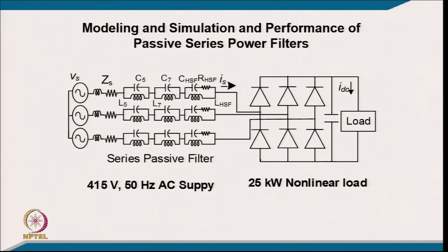Earlier only 2 diodes were conducting at a time, because out of 3 diodes, 2 are conducting, and sometimes even none of the diodes are conducting, because out of 120 degrees only 2 diodes should conduct at a time. Because of discontinuous current, sometimes none of the diodes conduct and the capacitor feeds the load, depending on the value of the capacitor and the load, the equivalent resistance, or the time constant. But now you are forcing all the diodes to conduct, and only then do these currents become sinusoidal.